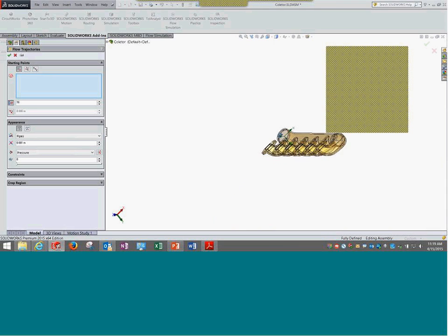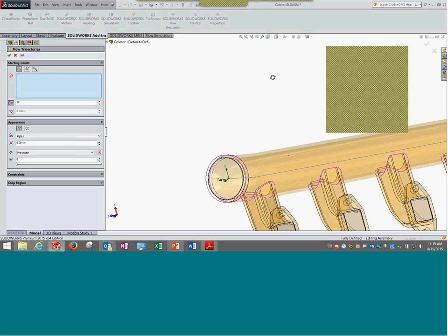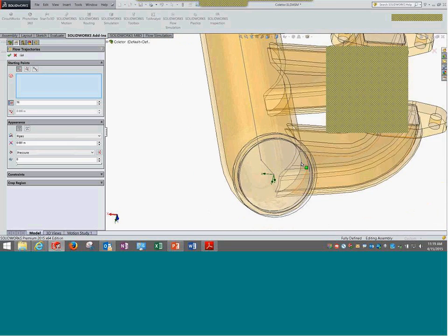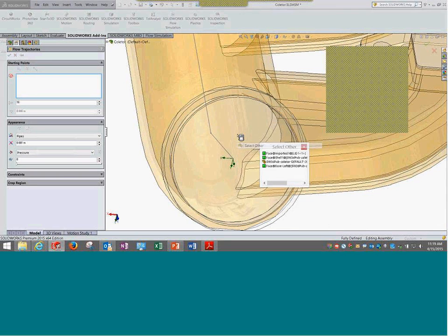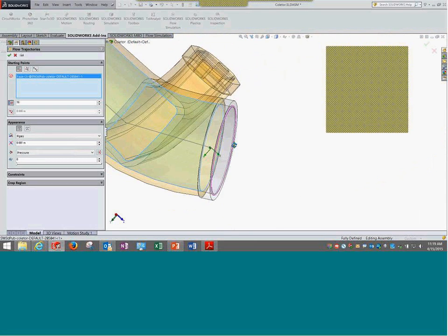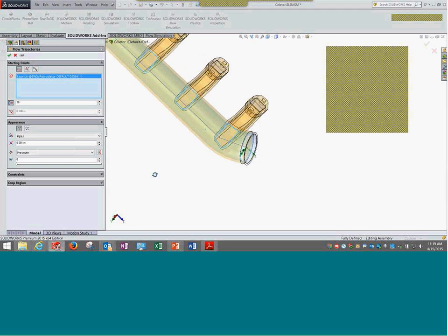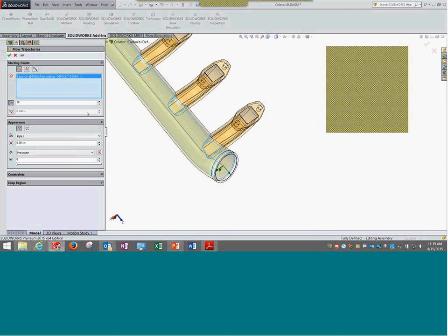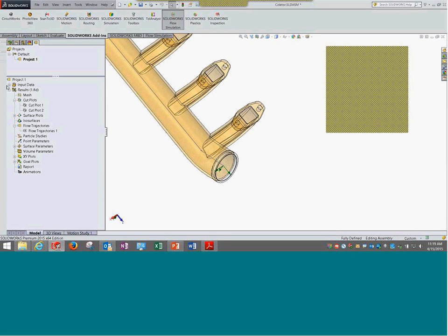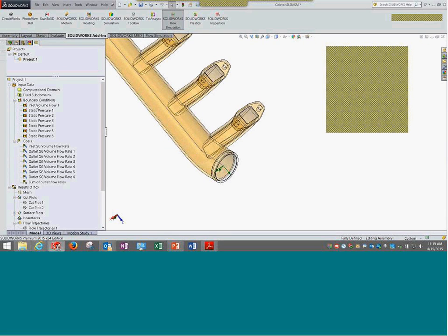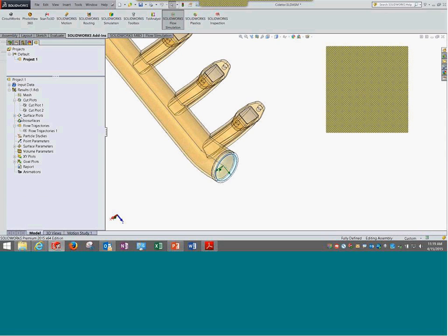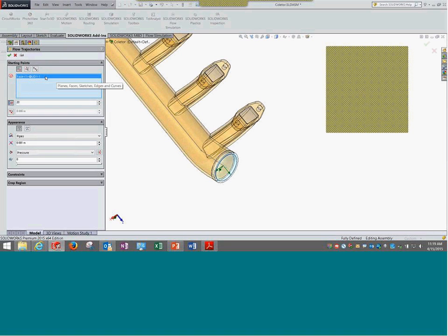Let me review and try to do it. Or I'll use a cut section or else. I think it is the internal surface. Oh, no. By the option to select such a surface, you can select the boundary condition. Okay, select the boundary condition. You can directly right click, insert. The automatic surface will get selected, in case you are not aware of this option.